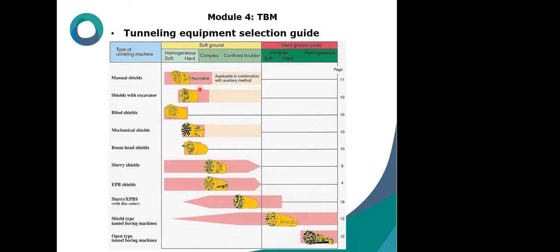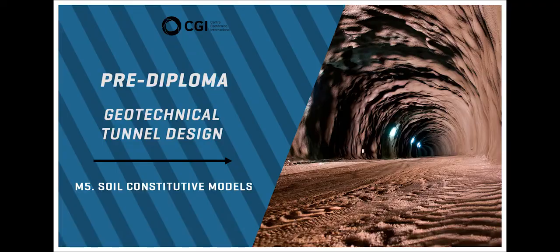It should be indicated that supporting systems in TBM differ from those in NATM. We don't have initial and final lining. We have segmental lining as both initial and final lining. The mobilized forces, therefore, depend on the construction method that we will talk about later.